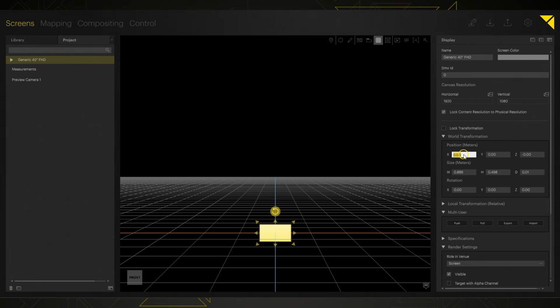One last really cool feature is I can click into this box one time and that will highlight this number. And then I can use programming syntax to do arithmetic to the number that is currently highlighted. The way that I do that is I would need to press 2 of whatever function that I'd like to perform on that value. So in this case, I would do ++2 to add 2 to the value that was previously highlighted, which was 0. And 0 + 2 is 2.